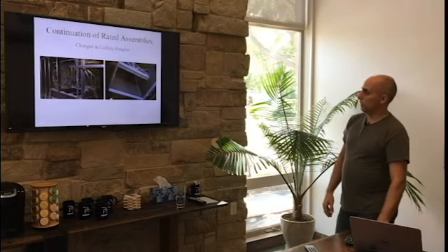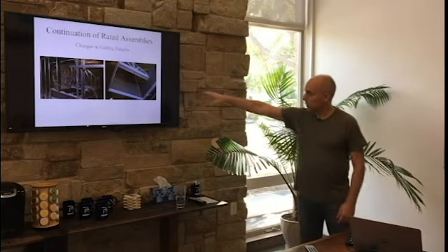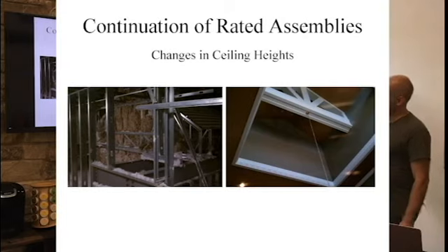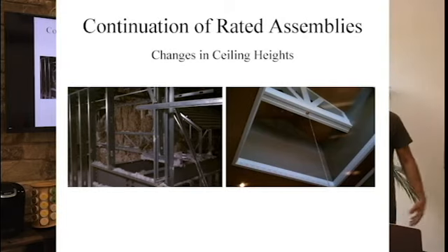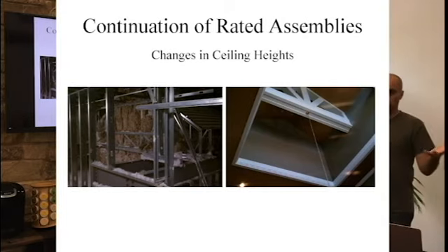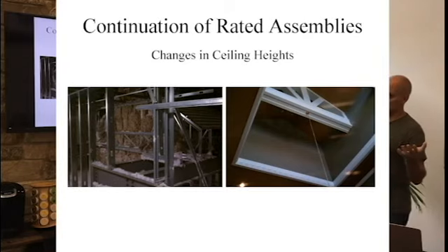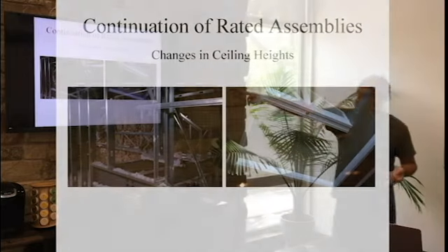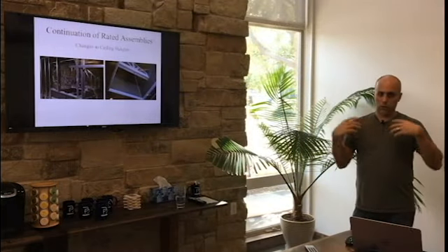And a good example, looking up at this on the right-hand side, and I won't tell you whose project this is or where it is, but those look like walls. And the uninformed gypsum rocker, the guy putting up the gypsum board, goes, it's a wall. So he puts up one layer on the inside, we're good to go. No, it's a roof. Because everything around it, what you're looking at behind it, in the left picture, is actually the structure. It's all trusses, all the way around it.